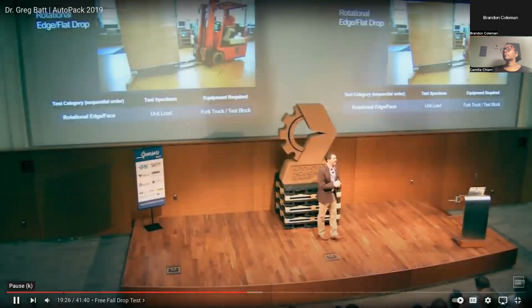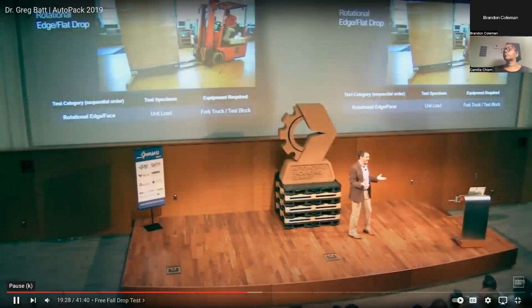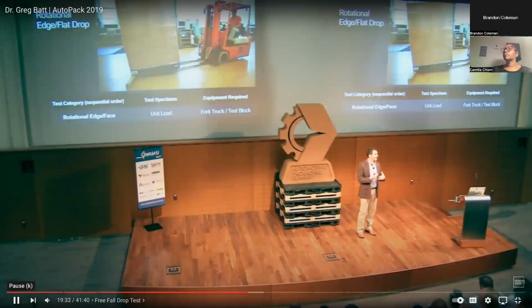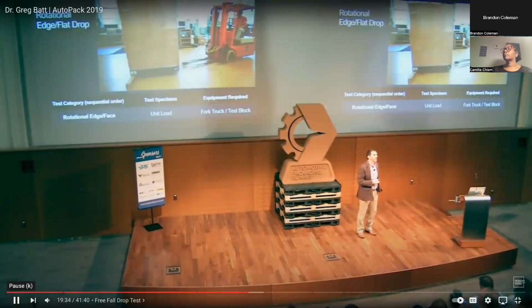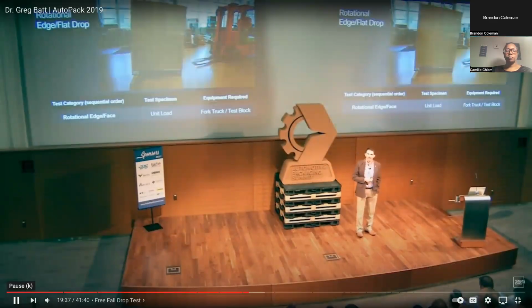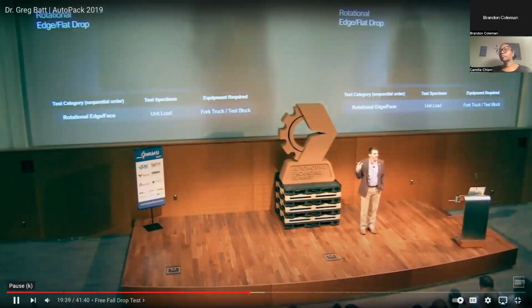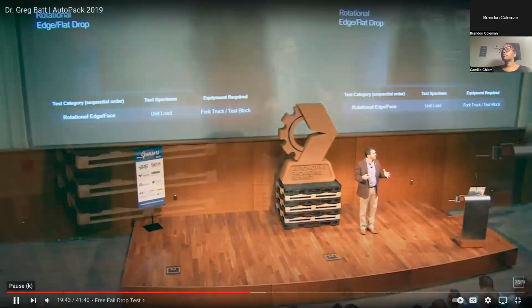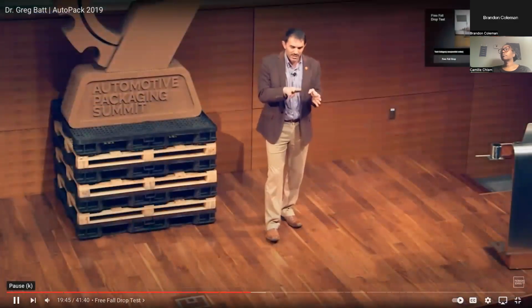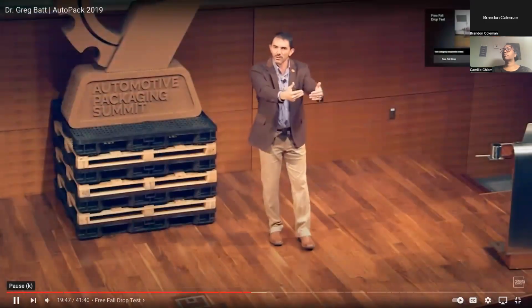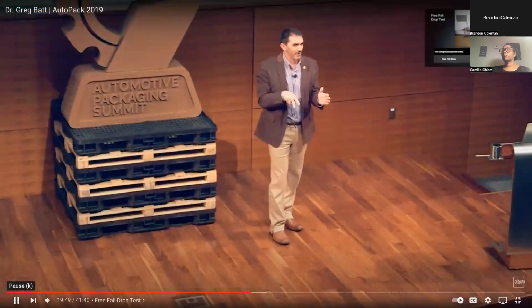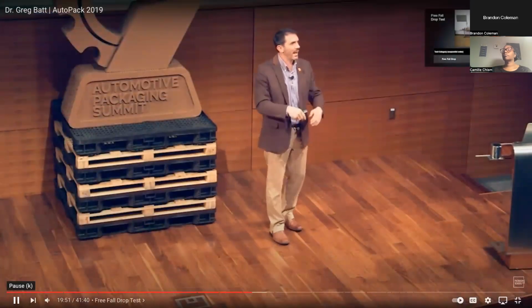Okay, another is, and this is a common one, you say, well, wait, can't I just do this out on my shop floor? Yeah, you could. I kind of loosely refer to these as the floor exercises of package testing. But if you look at them, they're practical, aren't they? Mechanical mishandling of unit loads, where a fork truck driver catches the back end on a unit load behind it, goes to slide the forks out and things rotate down and impact.